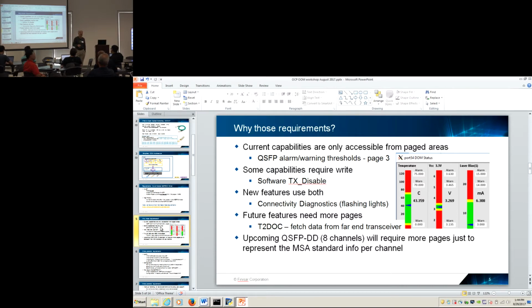Well, I think that colors whether you need a new driver and a new interface or not. Well, if you're going to use the new device and want this kind of data, you have to have a new driver. The old driver will give you some data, but it'll tell you the first 4 ports probably, but not the other 4 ports, because they're up at a page you can't get at with the driver. If you don't know ahead of time which kind of device is going to be plugged into the socket, then it seems like you want to have one driver that can cover them all.